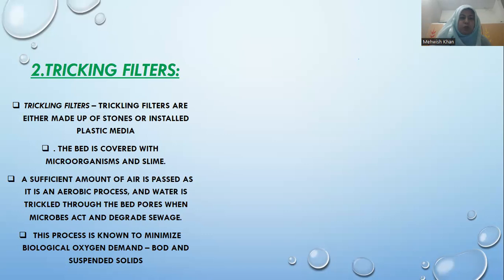It is basically composed of either stones, pebble stones, or a plastic media installed inside that filter. And the bed is covered with microorganisms and the slime that is to be purified, and the microorganisms will be used to convert that slime into an organic waste. This process takes place aerobically because the microorganisms use oxygen for proper functioning, and a sufficient amount of air is passed as it is an aerobic process, and water is trickled through the bed pores when microbes act and degrade the sewage.